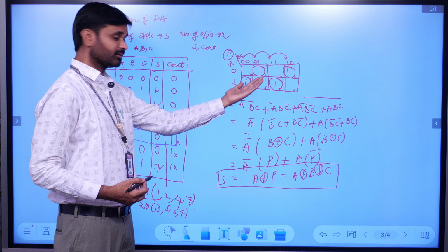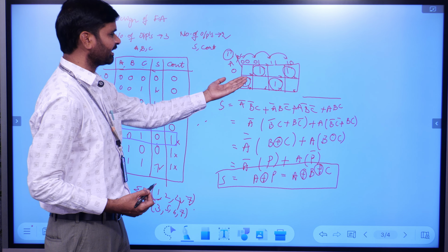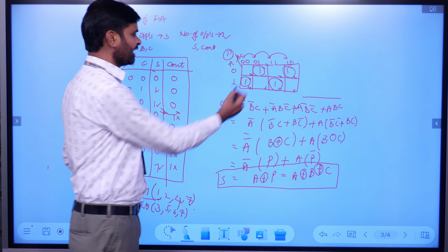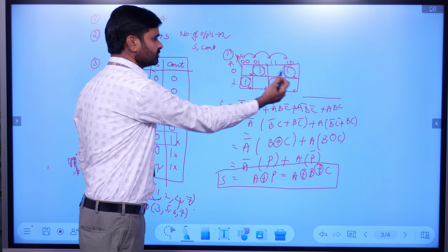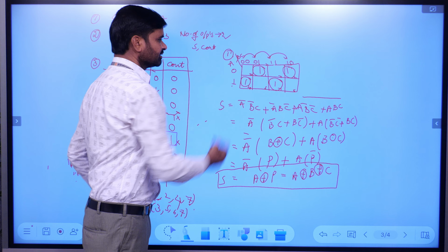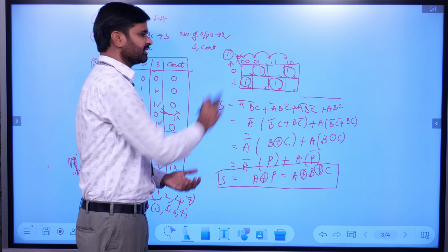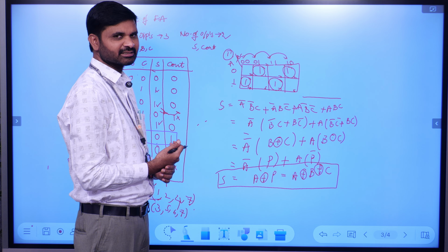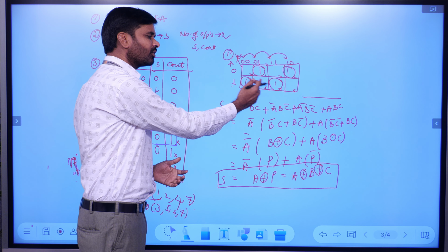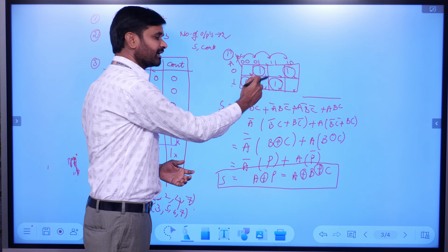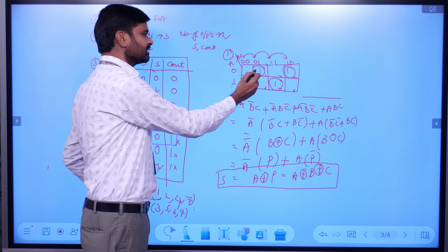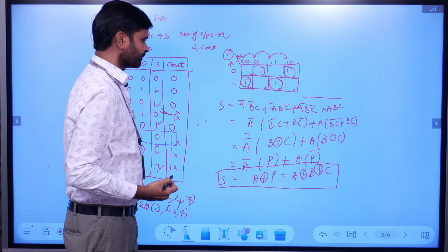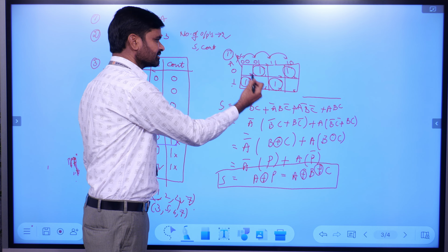So this is the Boolean expression deduction step where I have applied the K-map technique, as the number of inputs is more compared to the half adder. So I mapped the min terms 0, 1, 2, 3, 4, 5, 6, 7. In a K-map, if 1, 1 adjacency is there, I will group them as 2 min terms adjacency. But here no min term is a neighbor of another min term. So each and every one has no adjacency in the graphical representation of the K-map. So I have taken them as singular coverage elements.